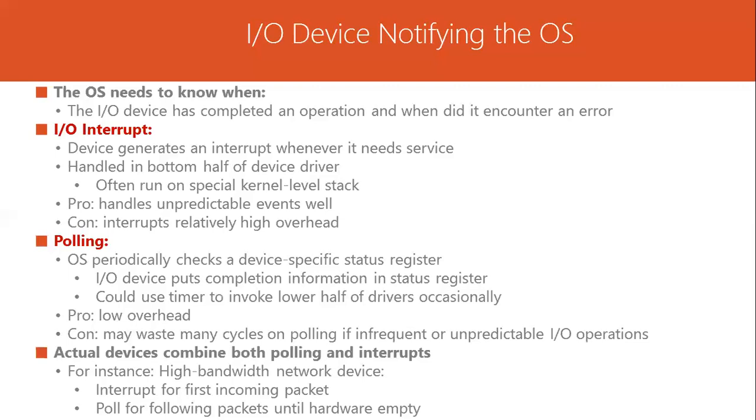I hope that you got the basic introduction into some of the requirements of the IO systems that are important to understand if in future you plan to write code for device drivers. We also looked into the different ways how a processor can access the registers on a hardware device and how the data actually transfers between the device and the processor. Then we talked about the DMA interface, which is a very fast mode of data transfer.